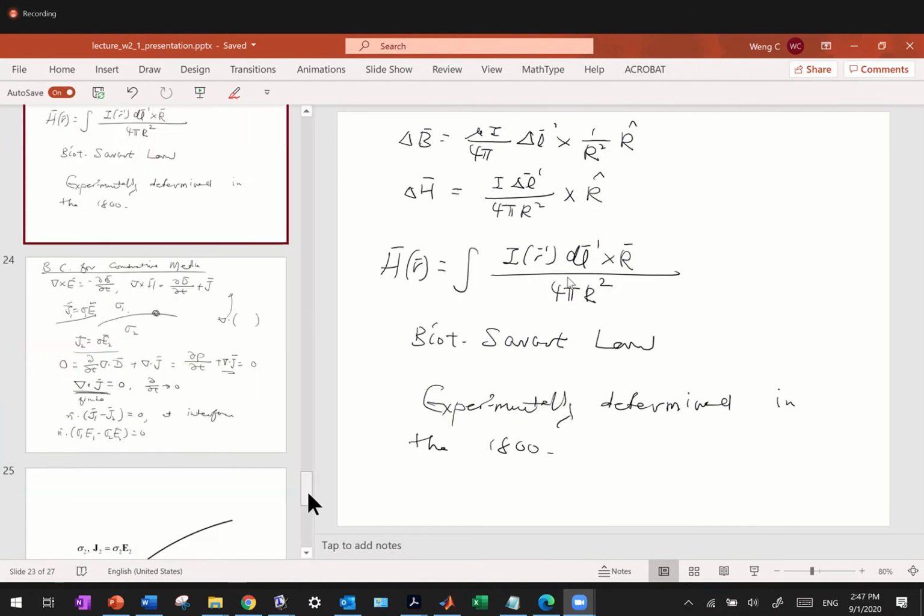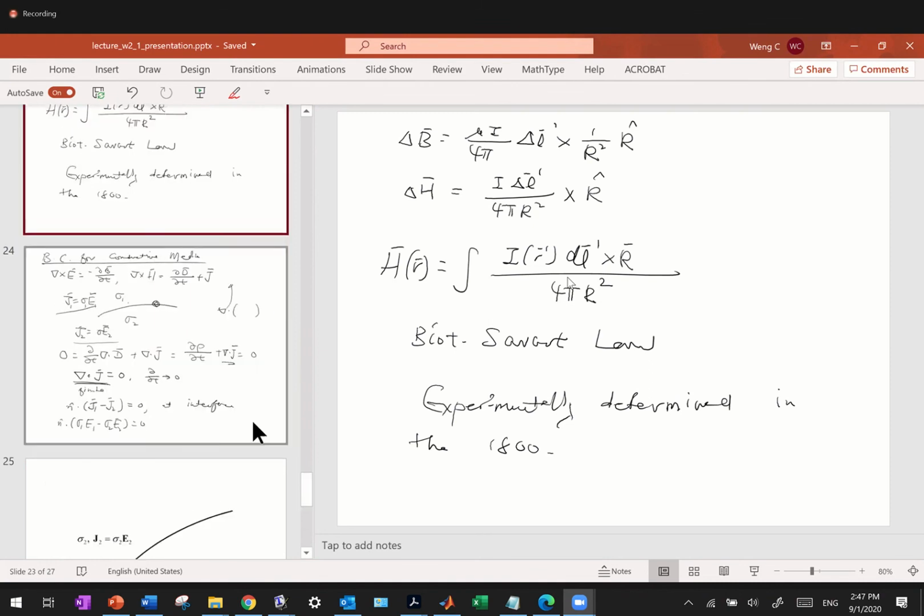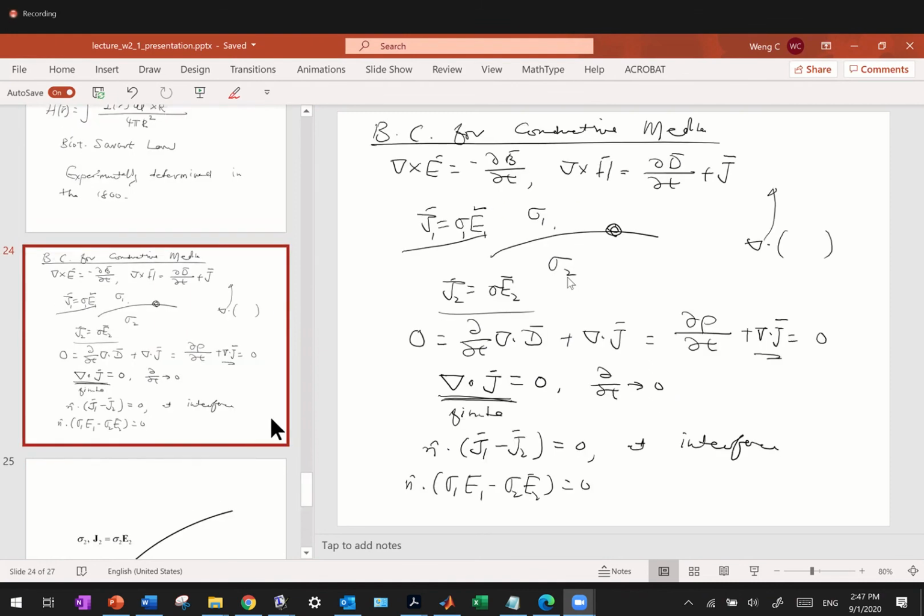So we go to the last case, which is what happens in the case of a conductive medium interface. In the conductive medium interface, there is this current continuity equation which can be derived from Maxwell's equations because this has to be the term with the highest singularity. Divergence of J equal to 0 means that the normal component of the electric current must be continuous.